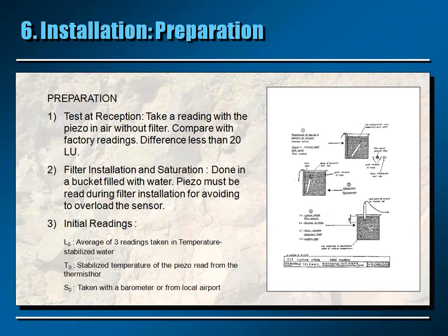and you put the filter back in place. With the ceramic filter, when you are doing that, you need to take readings of the piezometer. The reason for that is that since the ceramic filter is not very permeable, when you push it in place, this will increase the pressure inside of the piezometer. So you will need to make sure that this pressure is not reaching a dangerous level. It should not be higher than the range of the piezometer. Otherwise, there are risks of deforming or damaging the diaphragm. So this needs to be done.